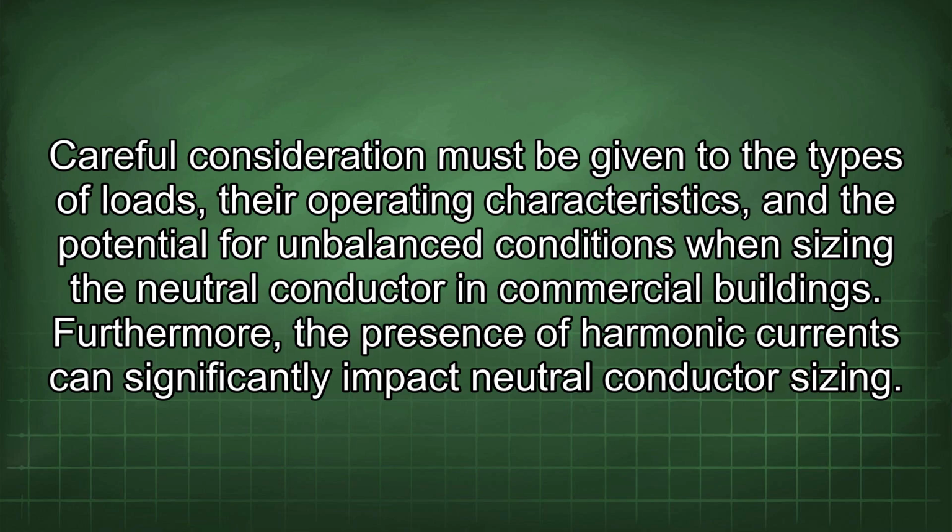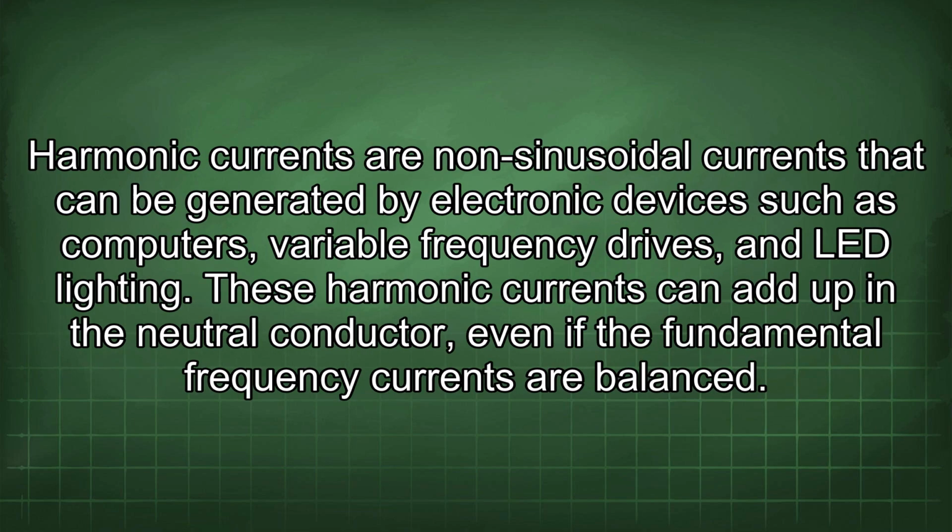Furthermore, the presence of harmonic currents can significantly impact neutral conductor sizing. Harmonic currents are non-sinusoidal currents that can be generated by electronic devices such as computers, variable frequency drives, and LED lighting. These harmonic currents can add up in the neutral conductor, even if the fundamental frequency currents are balanced.